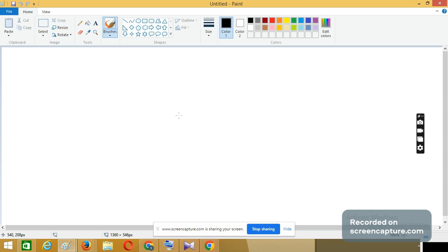After conversion, the ADC will inform through INTR bar to the microcontroller that conversion is over. After that, the microcontroller has to give information to the ADC to allow reading. So first it has to initiate, the microcontroller has to send a signal through WR bar to inform the ADC to start conversion.